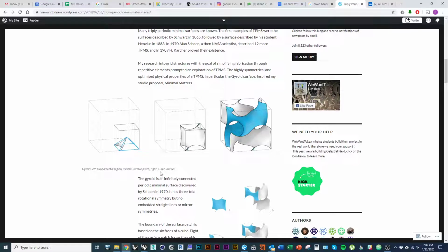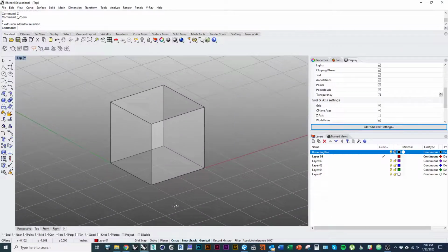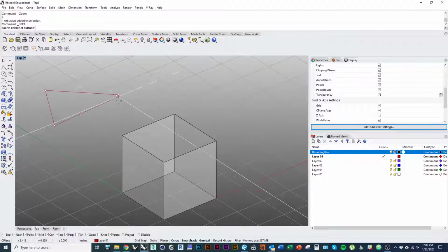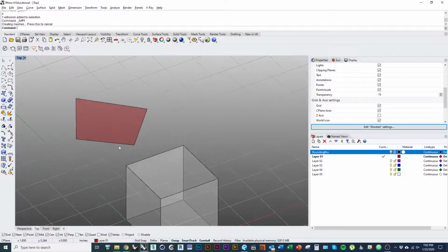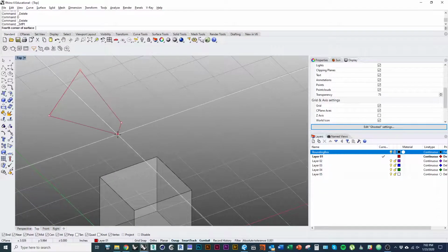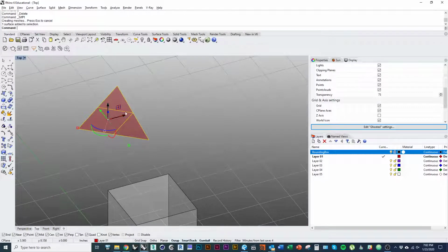And the thing about Rhino is, because of the way that you model with it, every surface has to have 4 edges. So for example, when I draw a 4-point surface, but I stop and press enter on the third one, and I look at those iso curves, what's actually happening here is I've created a trimmed 4-point surface.